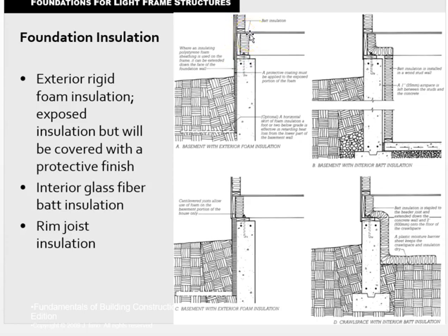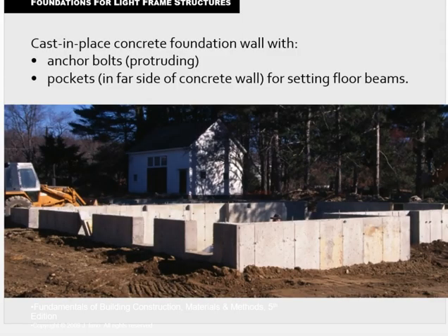In between two joists there's a bay, and at the end of that bay, down near the rim board, you'd call that the cavity, and that cavity should be insulated. Okay, moving on. So just some images now.